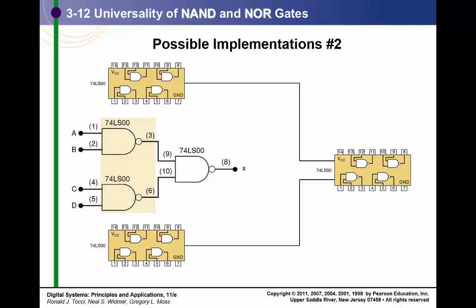As you notice, this part number is 74LS00. That should lead you to the understanding that 00 means that this is the first component in the family. This is the most important one. So when you do implementation out there, a lot of the engineers try to use just the 00 and nothing else, because that reduced the inventory in a factory that you had to have.